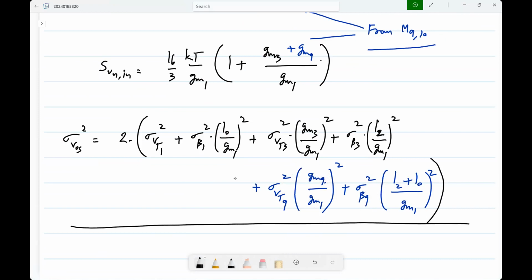So the main advantage is the swing. Other things are similar or worse, in that the output conductance is higher, the noise and offset are also higher, and two of the parasitic poles will be lower because you have more devices connected there and the devices are larger. So if you want some appreciable swing, especially with low supply voltages, you may have to use this.